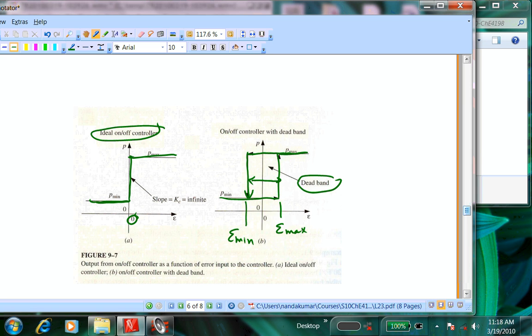The PID, right. So it's not the valve, but it's a controller that's cheap. The cost of the controller, like PID controller, will be much more expensive than on-off controller that controls the valve. The valve cost is going to be the same, but what you will find is the valve design. If you're going to require only on-off, you will design the valve to be simpler, meaning you don't need,